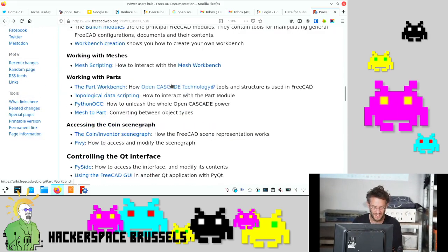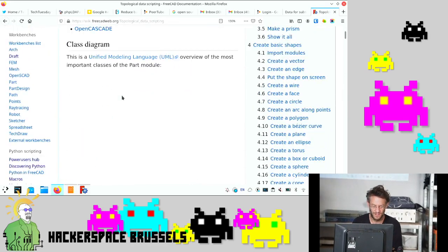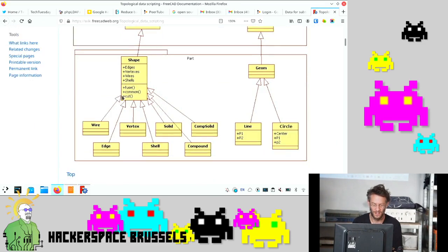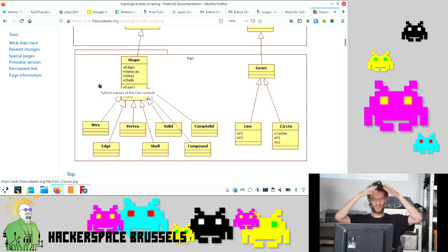We have stuff here. This is interesting. Yeah, all the way shapes are constructed. You have vertex, and between two vertex you can have a line or a curve. When you have lines or curves that form a closed shape, you can make a face. When you have faces together, you can make a shell. And when you have a closed shell, you can make a solid. And so it's all kind of a pyramid of elements, and that's how you build your stuff.